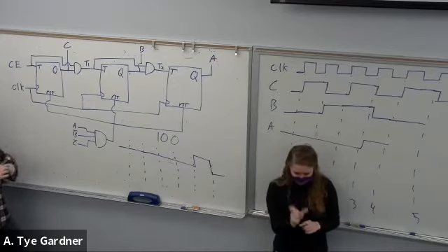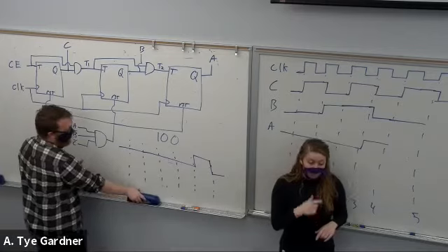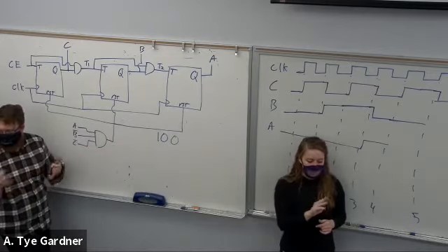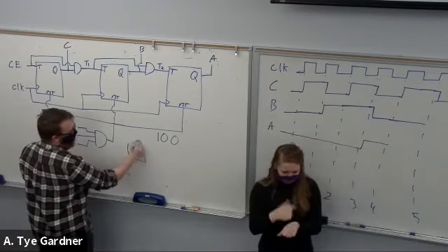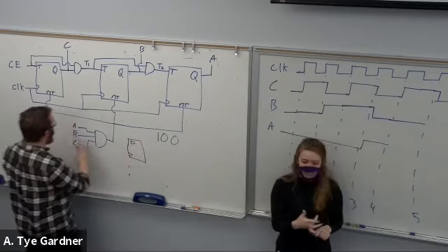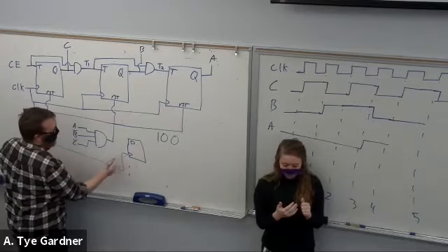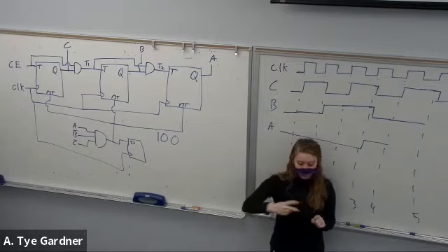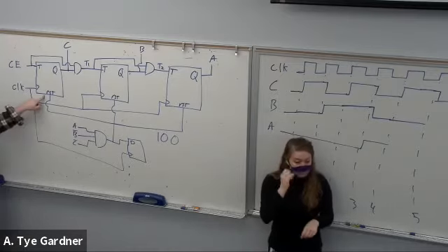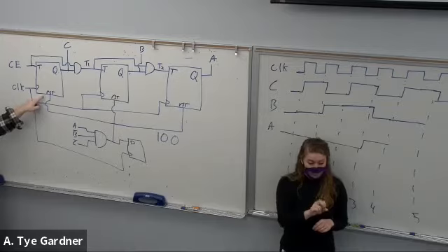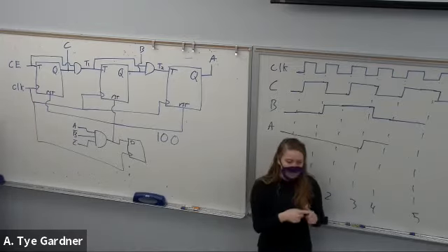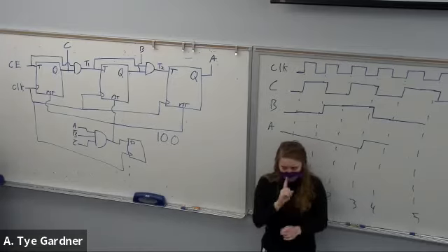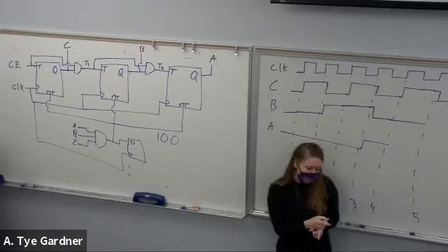It kind of depends. A lot of what I would do is for the real thing, because I don't like combinational logic necessarily as my output for a clock. So I'll attach it to a D flip-flop to make sure I hold on for one whole time, because if you have an asynchronous reset here, that will cause a problem too. And then the clock will delay by 1, and it should be right, I think. Oh, okay, then it'll delay the flip-flop.